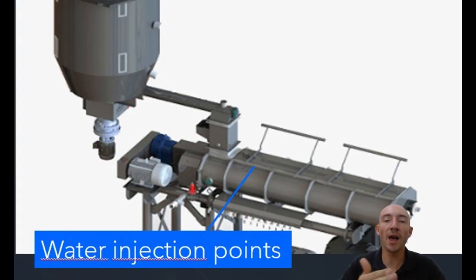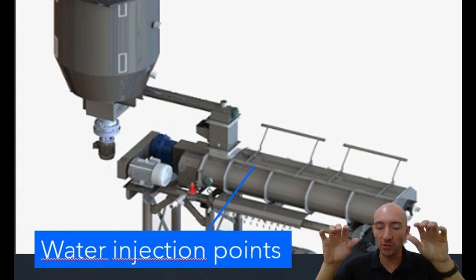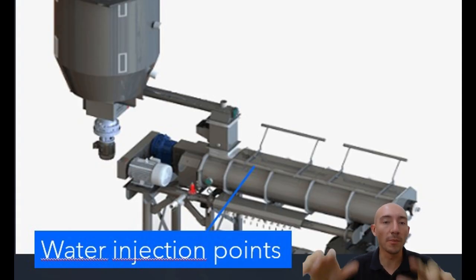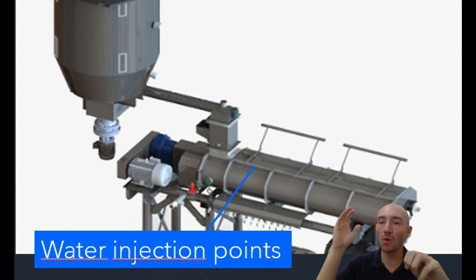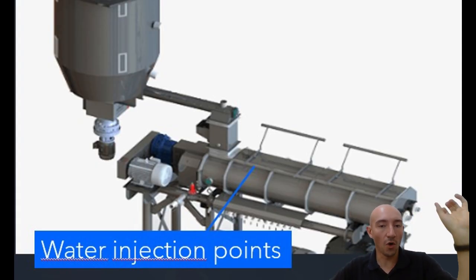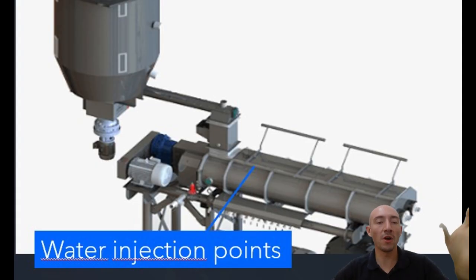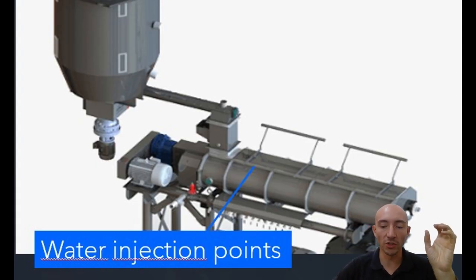So you want to have many nozzles of water along your conditioner to spray the water on top of your mash. The same concept goes for oil and other ingredients that you want to inject. The only difference is that oil you're going to inject at the far end of your conditioner, and water is going to be the very first thing that you add in your conditioner.